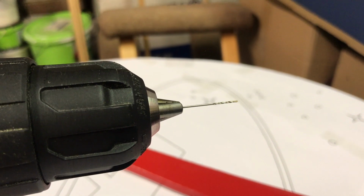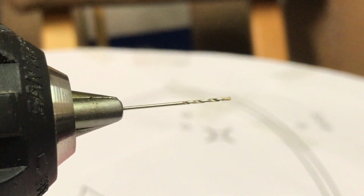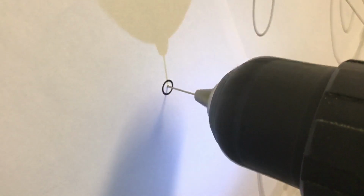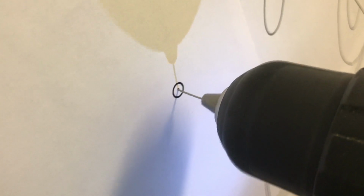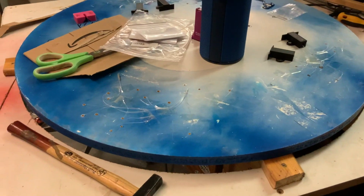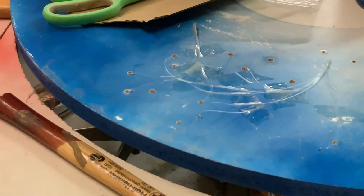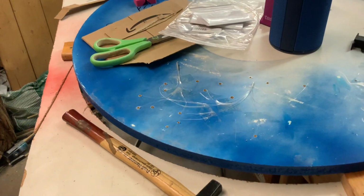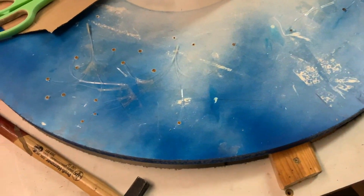To get all the stars to illuminate, of course, there has to be some way for the light to pass through. So this is why all over the base plate you need to drill some very small holes so that you can stick an optical fiber through. I started with a very small 0.5mm drill bit and later on went bigger. Unfortunately, I first started to just put the optical fibers through and wanted to bundle them in a single spot, but the super glue I used just melted all the fibers and it was a huge mess. So later on I stuck to the following method.